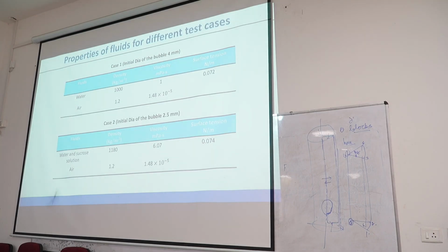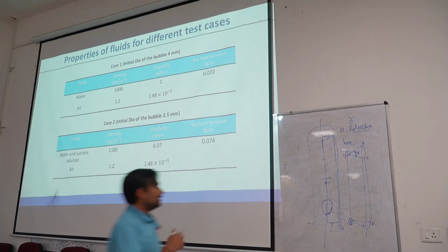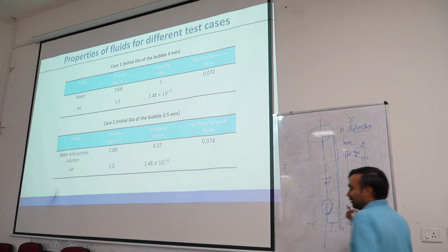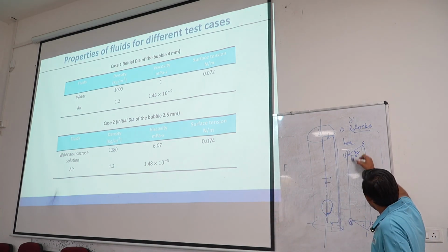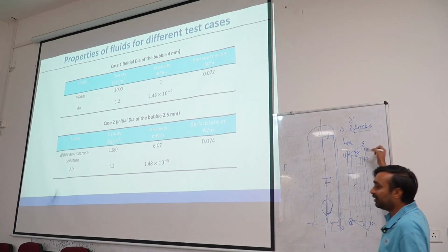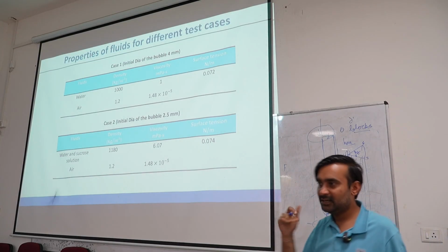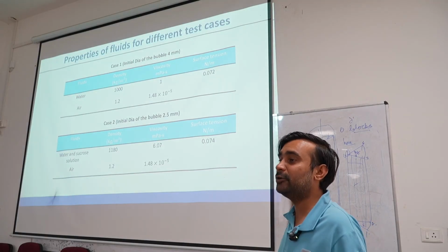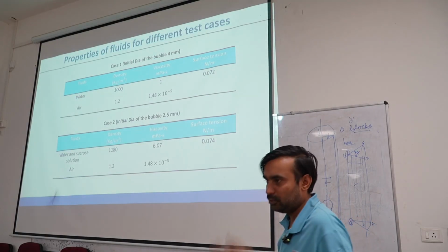Once these are common, instead of forming a hexahedra, this will form a wedge-like structure. On this wedge-like structure, because I need to solve only the axisymmetric solution, I will do grid refinement only in this zone, and in the angular direction I will not do any grid refinement because I need not solve the flow in the angular direction.